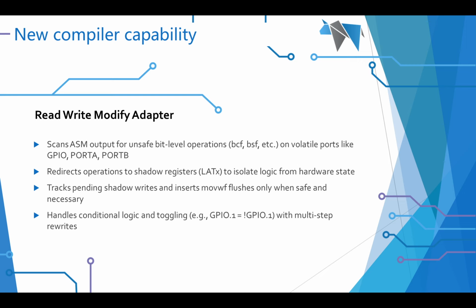So it handles conditional logic and toggling GPIO bits with multi-step rewrites. You could do it with one instruction, but you would have the potential of a read-modify-write issue. What we're going to do is expand that out to make sure it's correct.